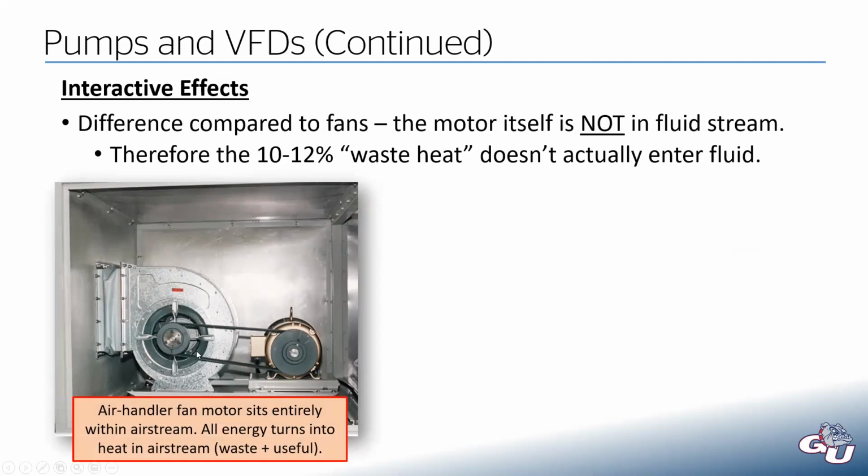So if you're staring right at this, this is the fan inlet. And this whole box around here is the casing of the air handler. So if our air is coming in from off screen over here, this is acting as essentially our ductwork. Then it's getting pulled into the impeller inlet right in here and getting pulled into this fan casing. And then it'll get blown out through this duct on that side.